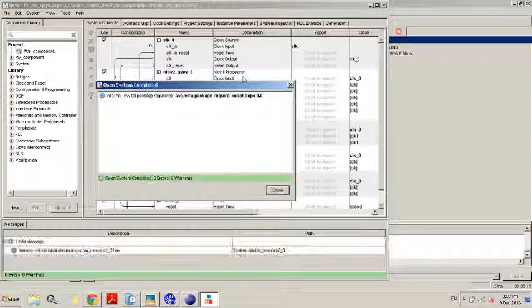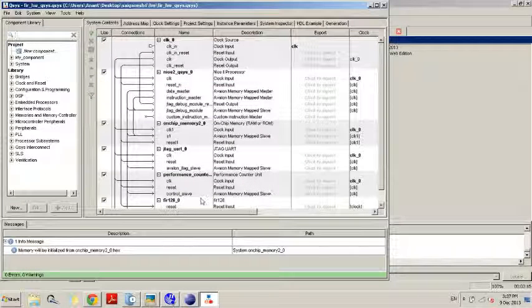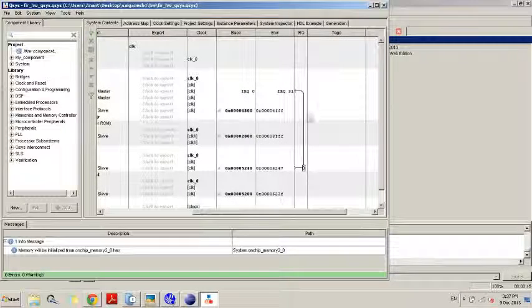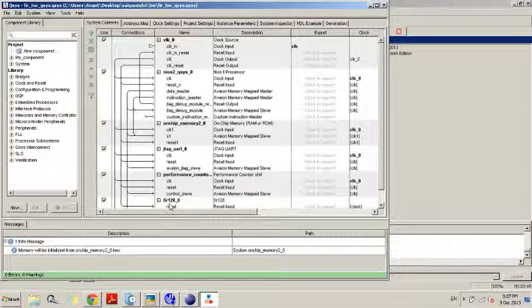Those components are Nios processor, on-chip memory, JTAG UART, performance counter, and a custom component named FIR128. Just as in the previous case, this Nios II processor is connected to all these peripherals using the data master. On-chip memory is connected to the Nios II processor using the instruction master, and the reset and exception vectors of the Nios II processor are set to that of on-chip memory. Clock and resets are connected properly, and the interrupt request is selected from JTAG UART to the processor.